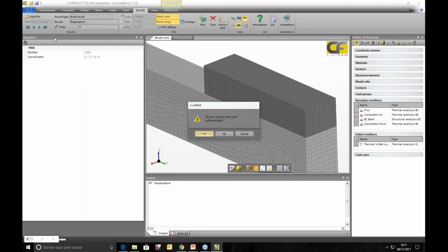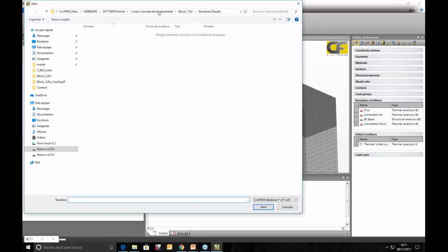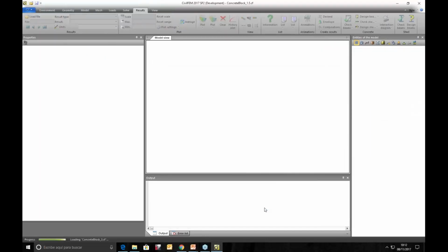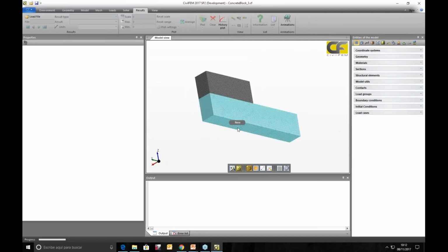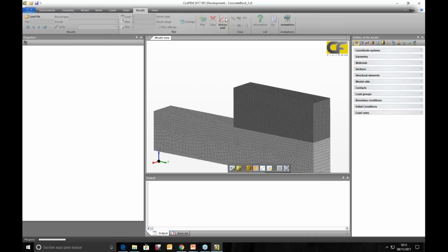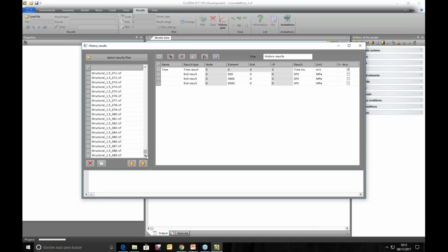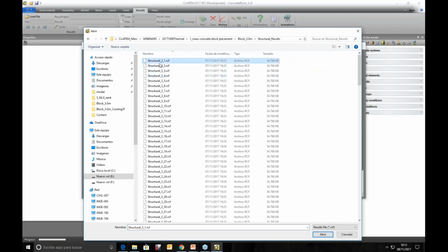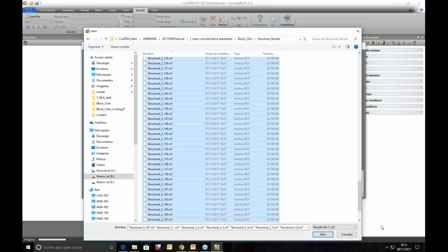Here you can see this one. We have solved for 1.5, 2, 2.5, and 3. So if we go to the last, all models are the same. So we are going to plot the last one. Here we can see in this last model, this is the highest thickness. And if now we plot stresses on the model in the same way we did in the previous one, the number of elements doesn't correspond, so I have to select new element numbers.